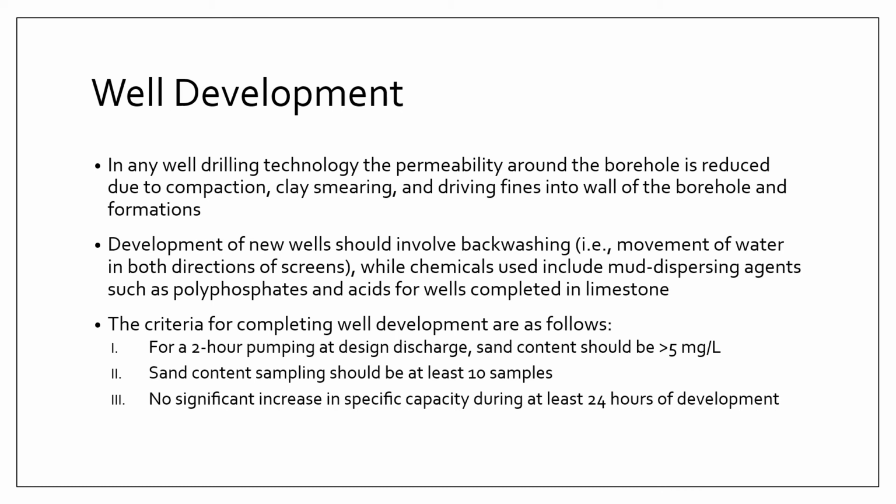Now, let's talk about well development. Well development is basically cleaning up the borehole. As you may know, well drilling involves a lot of mess, like compaction of the soils, smearing of clays around the borehole walls, and insertion of fines into the cracks and crevices of your aquifer formation.